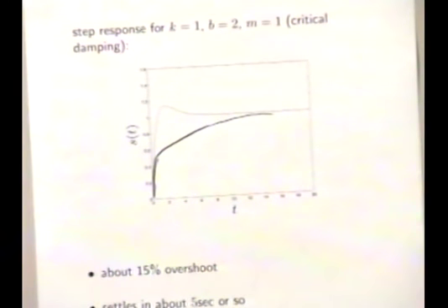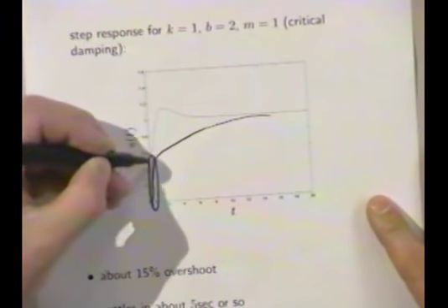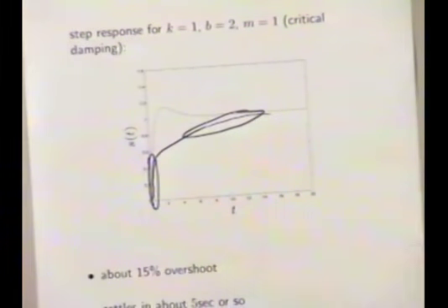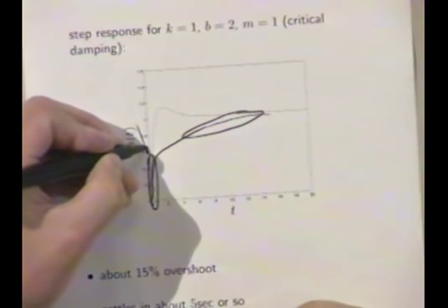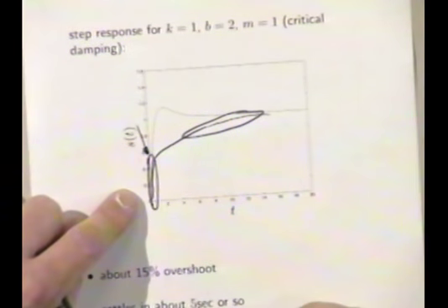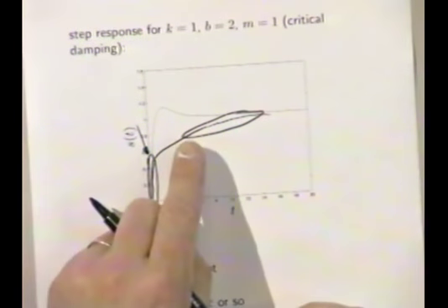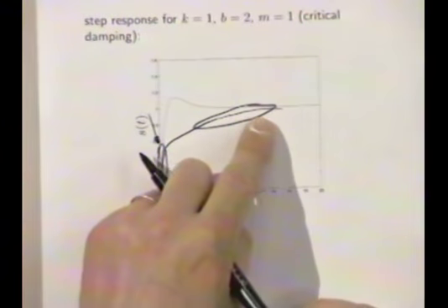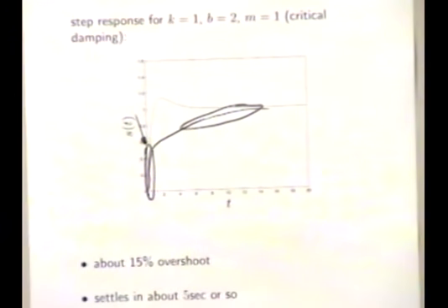Okay? So what you'd have here are 2 poles, both real. One would be relatively fast, that would be this one. And one would be relatively slow, that would be that. And this is the kind of thing you'd see. Right? So in fact, the disadvantage here is you'd get a bigger shock as you go over the curb. That's the first thing you'd notice. The second thing you'd notice is it would then take a lot longer to converge to the ultimate height. Okay? So that's just a rough idea.